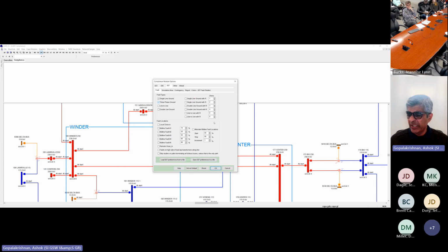First thing I'm going to do is set up the scenario that I want to run. I'll take you through some basics. I hope you can see this clearly. So you remember how we want to consider different fault types and fault locations and so on, right? Here I'm looking at a single phase to ground and a three-phase to ground fault. Those are commonly studied by protection engineers. You can add other fault types as well, and you can add faults with resistance or arc resistance, which are often evaluated by engineers. Right, so those are the fault types.